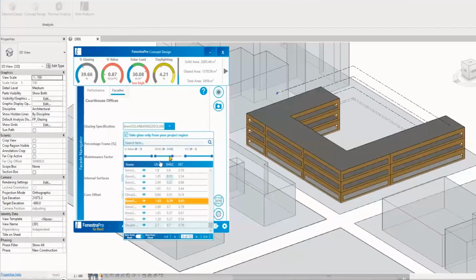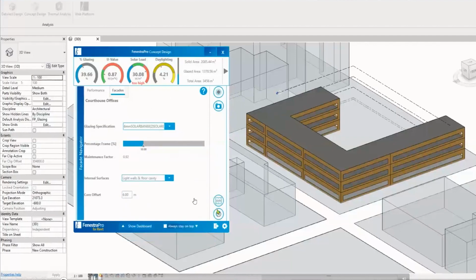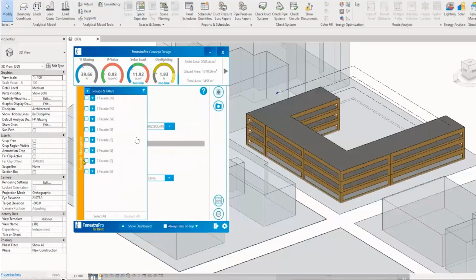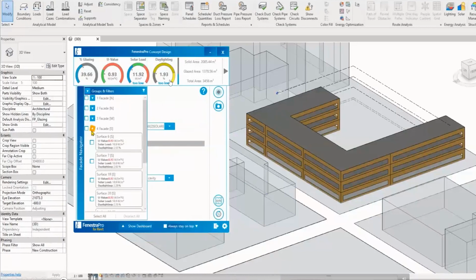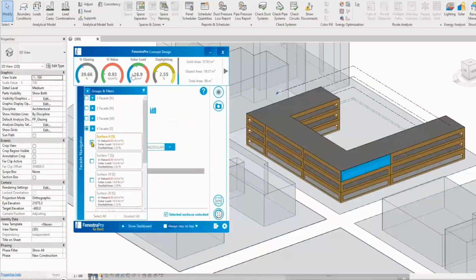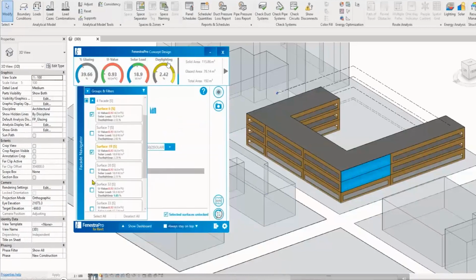We can select that, and we can filter based on your solar heat gain coefficient, your VLT, and so on. And then you can also select the various different available glass types, apply that to the project, and look at the impact it has when you recalculate those values within the application itself. So you can see here, by using that particular glass, we are reducing our heat gain down a particular level, and we can see that the daylight is coming down as well.